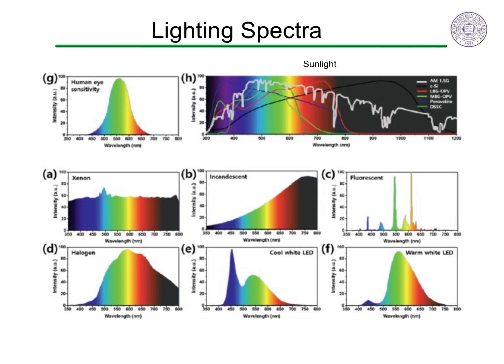The fluorescent lamp requires a voltage regulator or ballast to make an electric discharge in a mercury vapor. The ultraviolet light produced excites a phosphor that gives red, green, and blue light that appears white. The sharp peaks are due to atomic transitions of defects in the phosphor, which are engineered to be at the right wavelength.